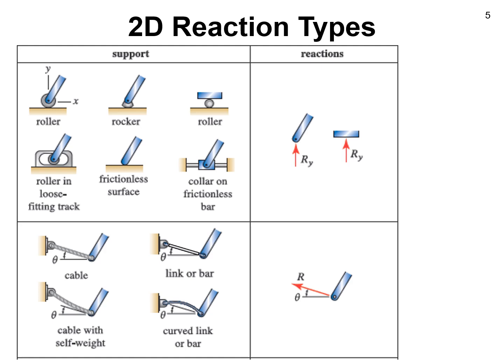In the reaction column, you see that all of these different symbols indicate that the ground, in this case, can exert a force normal to the surface because it can resist motion in the vertical or normal direction, but there is nothing to resist motion in the tangential or horizontal direction, so there is no force in that direction. We'll summarize this: these supports can transmit a force that is normal or perpendicular to the contact surface and nothing else.